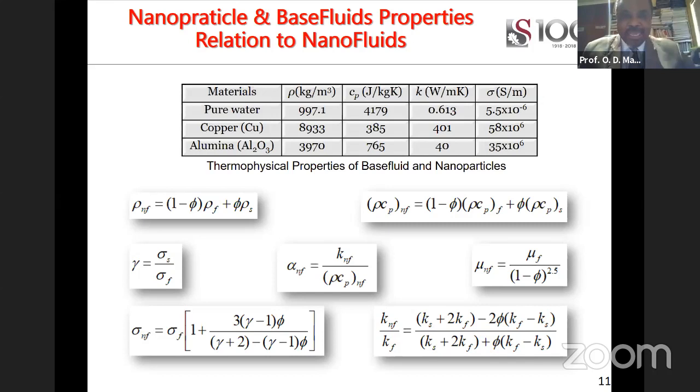And you can also see the heat transfer rate in all this. What is the effect of magnetic field? Will magnetic field affect this one more than this? Will this give a better result than magnetic field? Because magnetic field is important for flow control. If you pour a fluid to cool a surface, the fluid flows very fast. The heat will not be taken away quickly. But when you use magnetic field, it can slow down the flow rate, because the Lorentz force will oppose the flow. Depending on how you apply it, you oppose the flow and reduce the rate so that the fluid can take out the heat from the surface more and better.